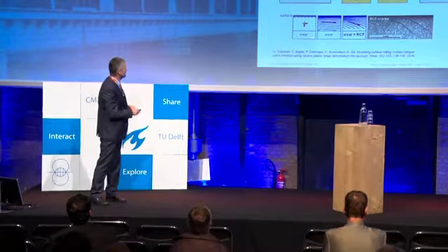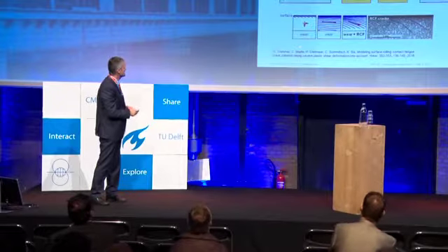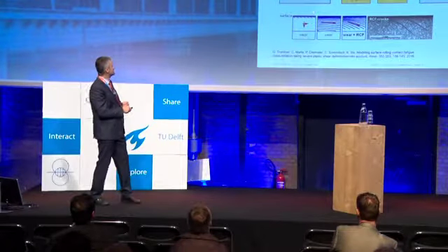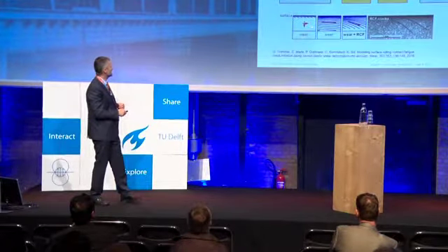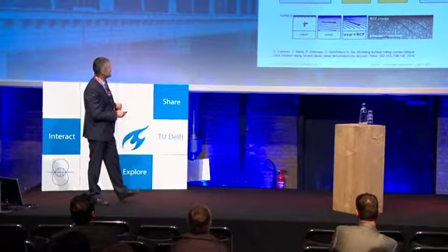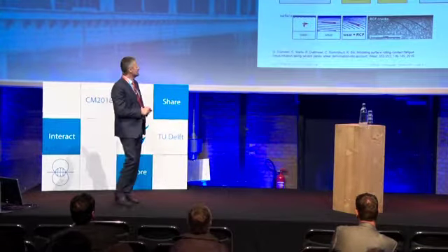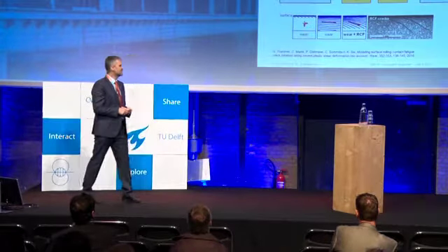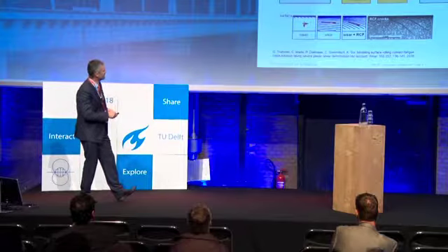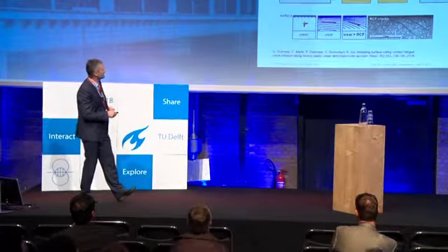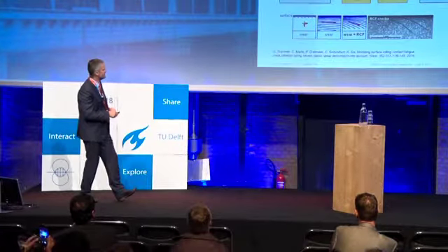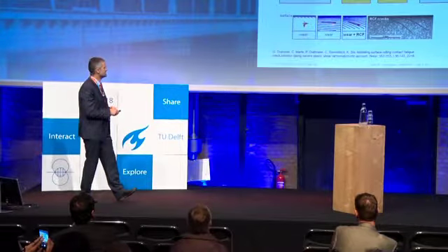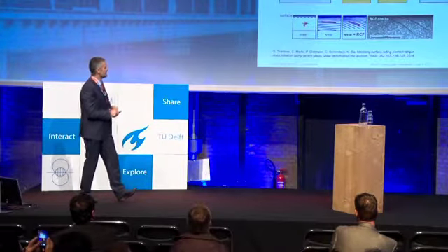We distinguish three main cases. The first case is with low loads, with no preferred crack growth direction. This is a wear-only case. The second one is huge loads, where you have a very severely plastically deformed material layer on the rail surface, so you have a preferred crack growth direction, but the cracks grow parallel to the surface, and they produce mostly wear-only cases because they break off.